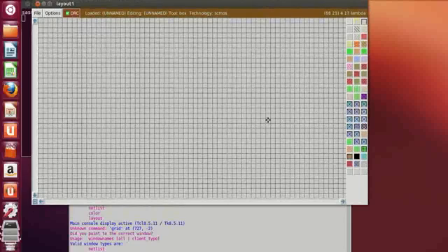So if you want to draw the layout from the twisted schematic, then it's very easy for you to draw the layout. So first we have to draw the PMOS, then the NMOS. Since the function is A plus B plus C bar, that is A plus B plus C, the OR operation, the PMOS is in series and the NMOS is in parallel.